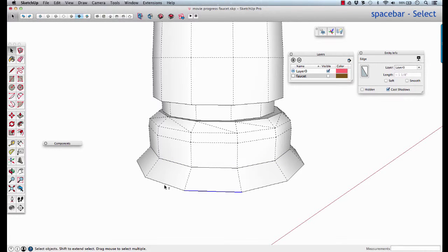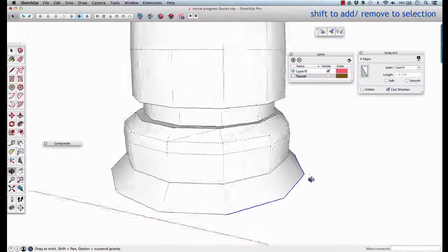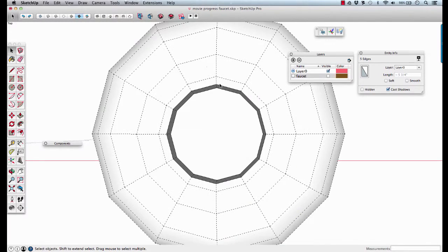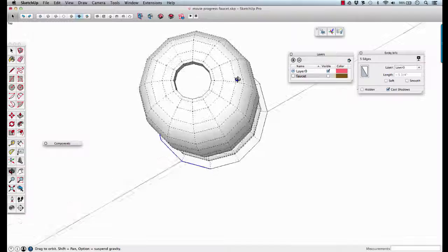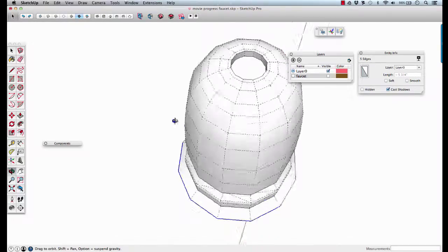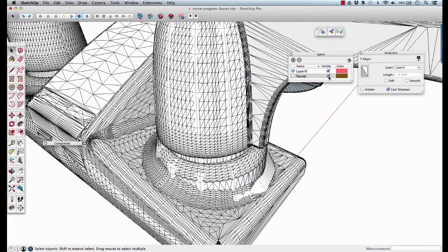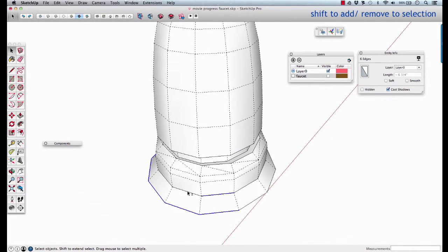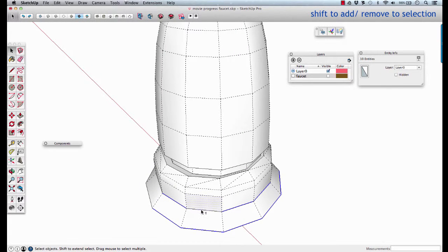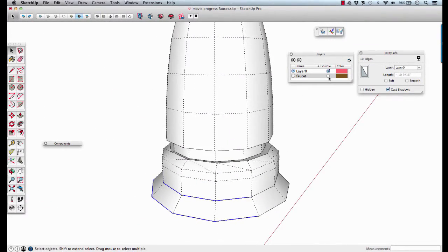Now we'll just select portions. So I'm just selecting edges. And we'll move those up as a group. I'm going to go to a top view and see if... Okay, I'm trying to stay symmetric. My selection, turn on the faucet. Actually, hold down Shift. I'm going to select single edges just above it as well. So now we'll move those all as one set upwards to begin with.